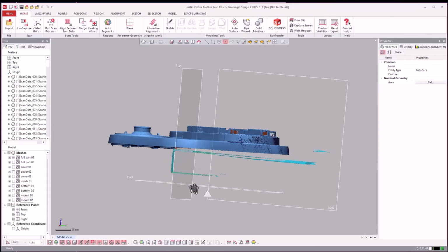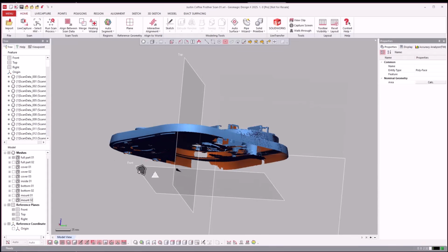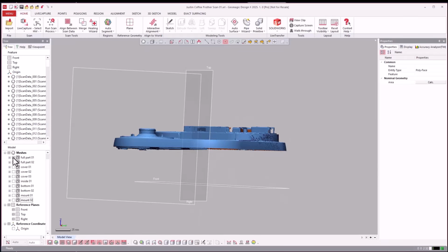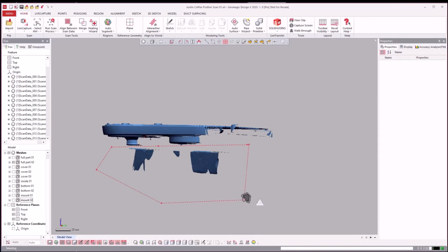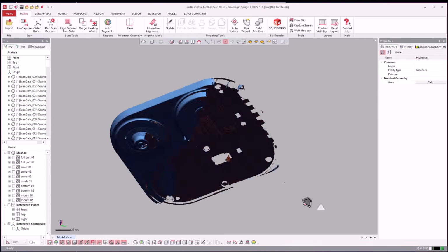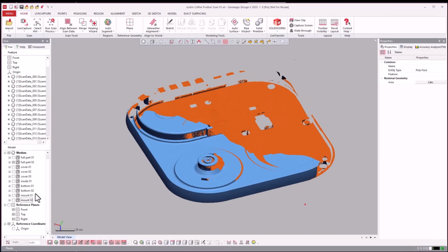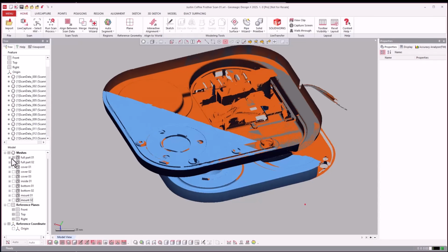And select and delete all the components. Especially if you're over scanning, you have plenty of data there to be able to select and delete what's there. So you see there, I just went ahead and I took that scan and I cropped the table away. It only takes a second to do. And same thing goes here. We'll go ahead and hide my planes as well, and select those and delete those. So now we have the top and bottom cleaned, right?